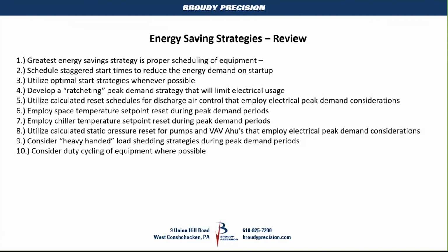And even in the wintertime, if we have electric boilers, we can reduce our heating set point. And it's not forever, it's just while we're in a high demand situation. And that is to keep our instantaneous energy use as low as possible.